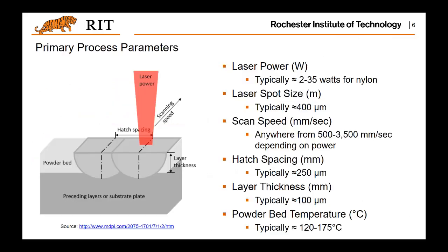As you can see here in selective laser sintering, what happens is similar to stereolithography. A trace of the scanned region will be consolidated. Again, you have the hatch spacing, which is similar to the pitch in the SLA process.